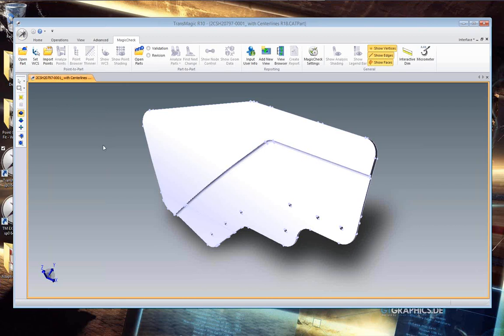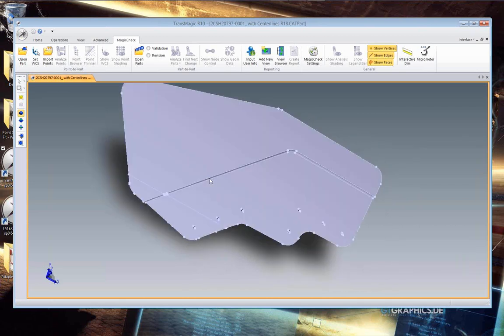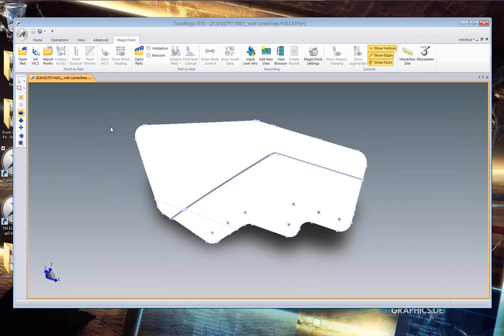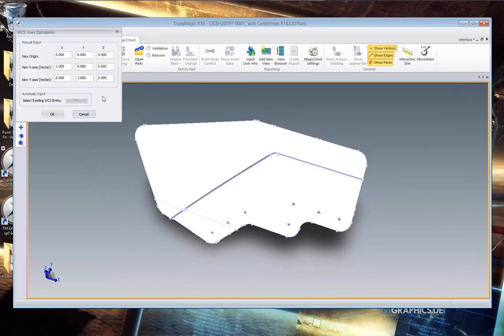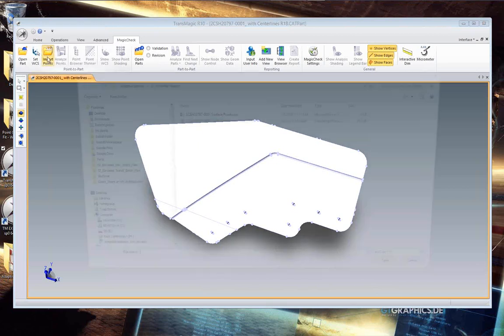This is a working coordinate system. This is sort of the datum where the point was measured. This particular example, it's a real-world customer file, does not have that. So what you would need to do is have established your measurement datum, and you can key that in manually here. This one just happens to be at the origin, the same as the CAD origin.